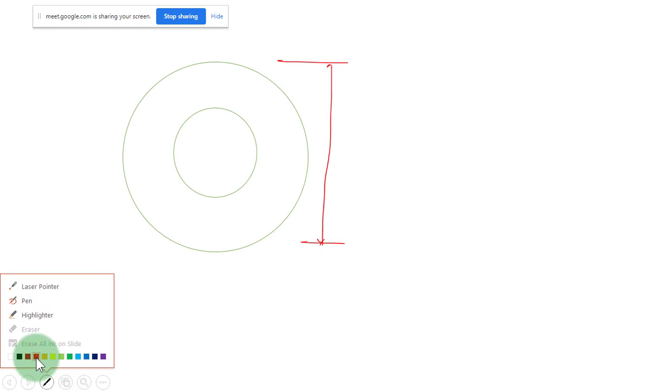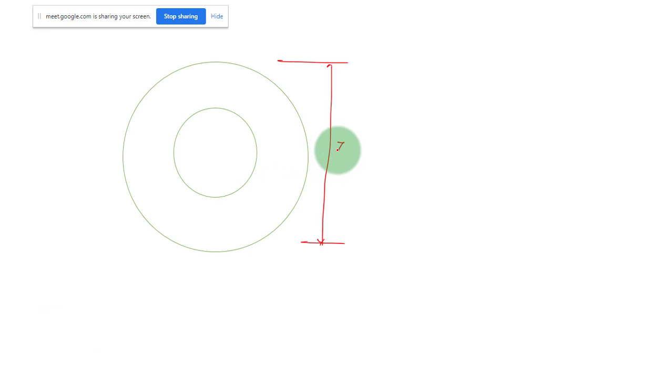So in this section, let us say the outer diameter is given as 75 millimeters and the inner diameter is given as 50 millimeters. You have to find the shape factor. Again, it is also homework. You can just find out Zp by Zd, and Zd you find out as the moment of inertia I by y max.